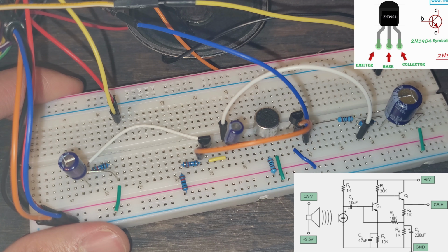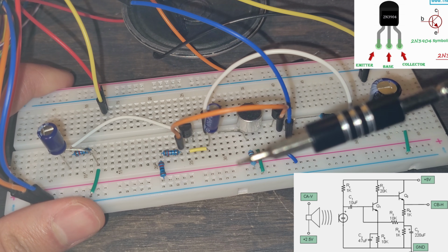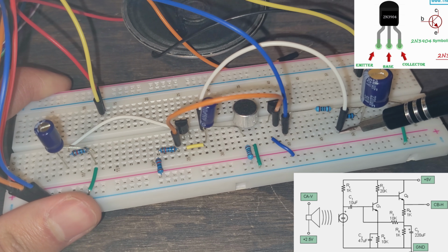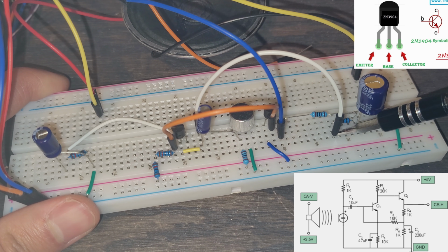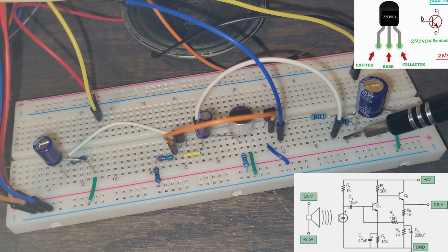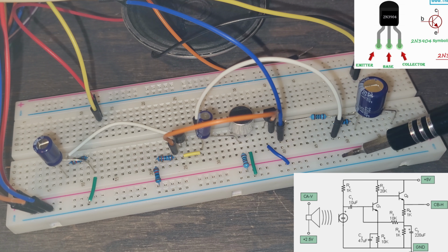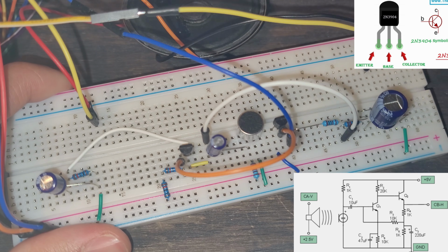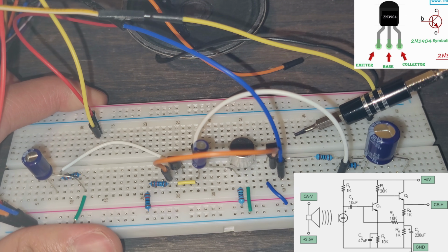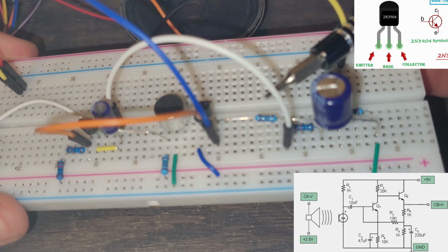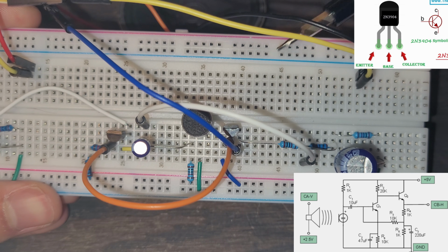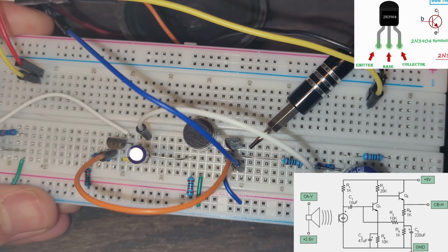Let's keep looking at this. From the 10 microfarad capacitor, remember we said it's this one, we have it connected to a 10 kilo ohm resistor. Right above that, we can see it's in parallel with a 1 kilo ohm R4 resistor, right? And that's coming from Q2. Our Q2 is this transistor, and it's coming out of the emitter. The emitter is going to be the very far right, so it's going to be this one right here.